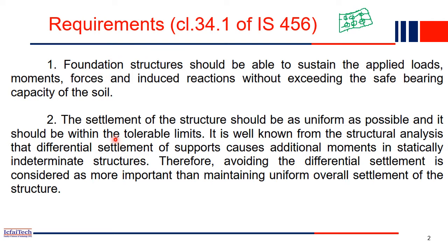Below the ground surface, there will be soil structure interaction also. So the foundation structure undergoes soil structure interaction. Soil will be surrounding, and then you have the structure, right? But in the superstructure, there is only structure, there is no soil all around. Here the foundation is covered by soil, so soil structure interaction will be there. That also we have to take care of additionally.